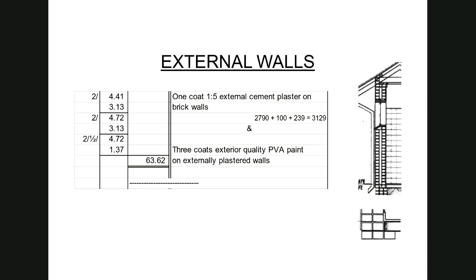Right, so I'm going to deal with the finishes on the external walls first. Just as a reminder, this cut and paste that I have at the bottom over here is detail X. So I just wanted to remind you about the 100 millimeters that I have over here. Now for measuring plaster, the requirement of the standard system for keeping beam filling separately from the other measure does not exist. That applies to face brickwork only.